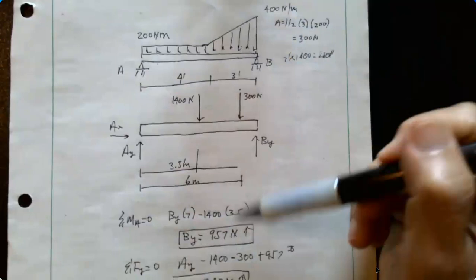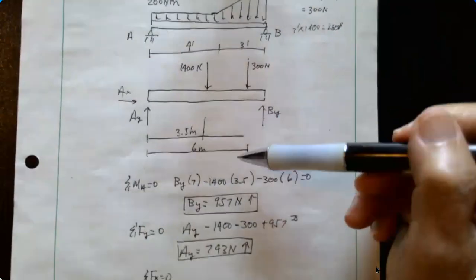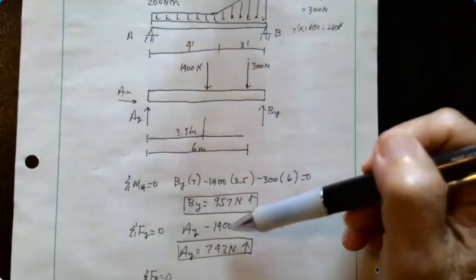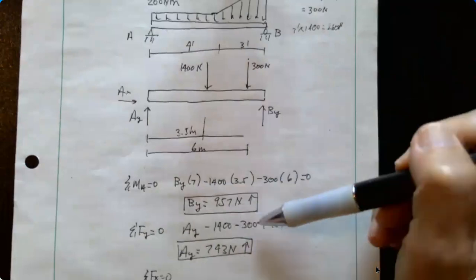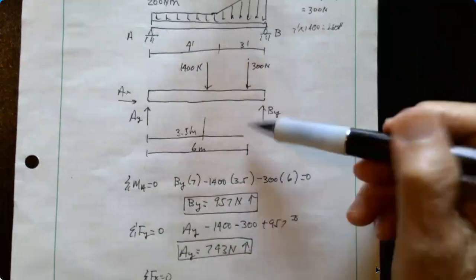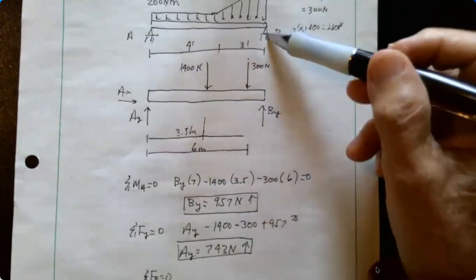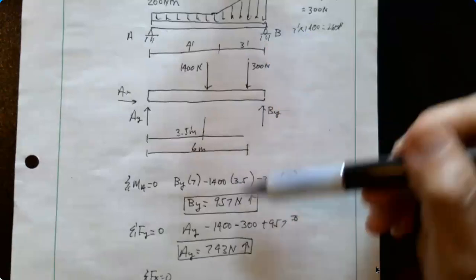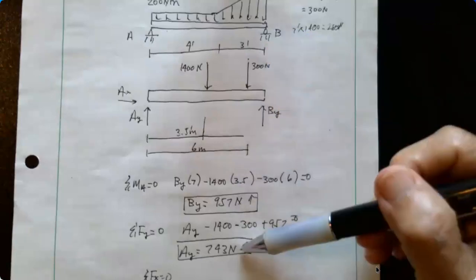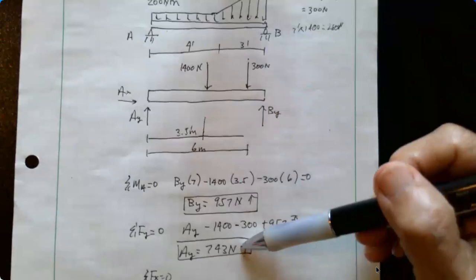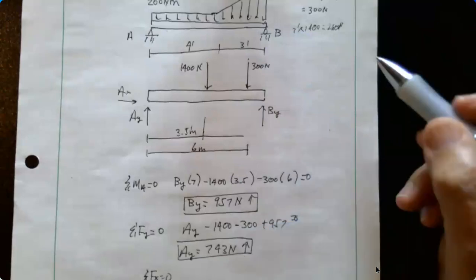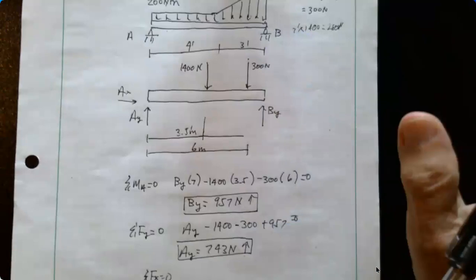If you want to check, sum of forces in the y, get A sub y. If you want to run a check on this, take moments about B, and you should get what you found for A. That's one of the checks you can do on an exam.